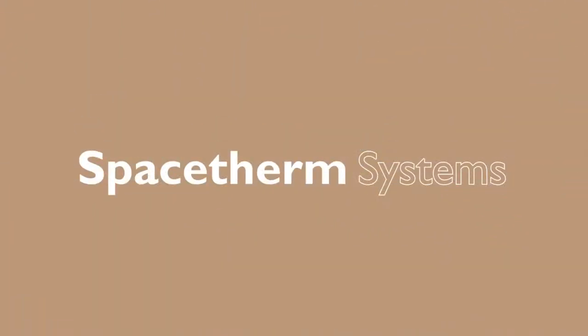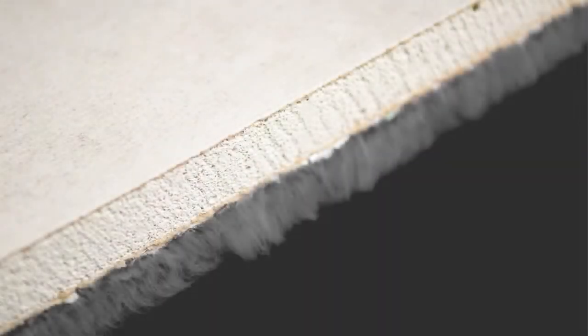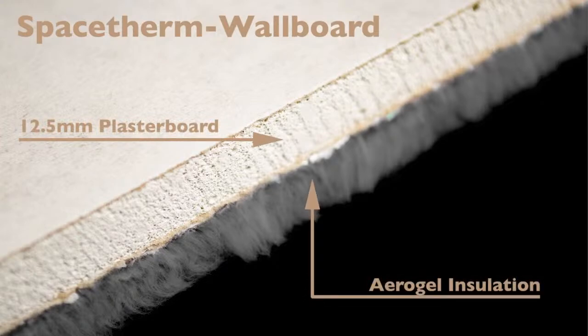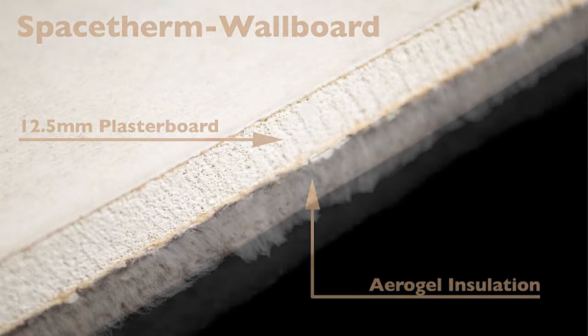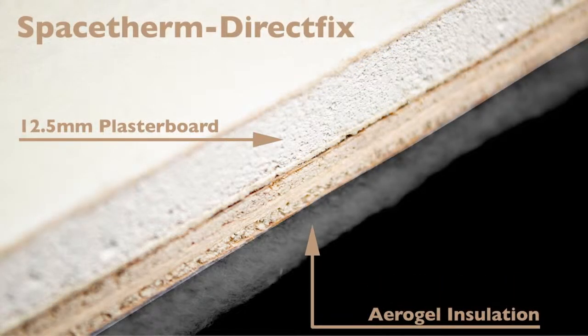Spacetherm Wallboard and Direct Fix. Where a more traditional finish is required, Spacetherm Wallboard offers a plasterboard finish with the same aerogel insulation as the multi-boards. This is fixed onto timber straps or studwork in the same manner as traditional insulated plasterboard, but offers significantly better performance. For applications where space is even more constricted, Spacetherm Direct Fix can be used to omit the requirements for the timber strapping and its associated depth.